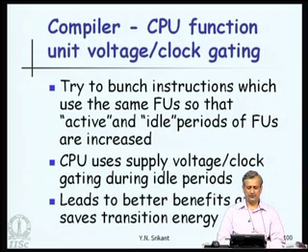This technique can be used both for voltage gating and also clock gating of the CPU. Now, we try to bunch instructions which use the same function unit, so that the active and idle periods of function units are increased.